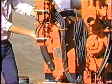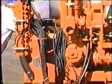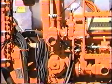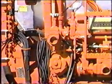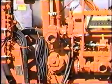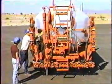It's identical as far as swivels and seals. Hose up to a T, and that T is right where the butterfly valve was that we started out with. Remember, we called that the main equalizer valve. It's still in the closed position, so it can't go through that butterfly valve. It has to come out this way through the T and up this line.